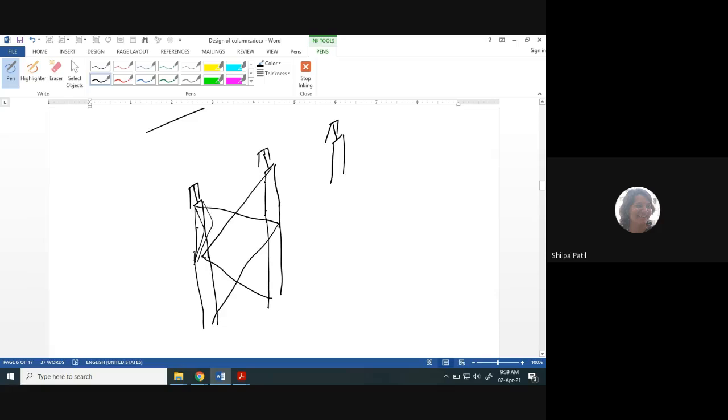Okay, here also, if the column will buckle, it will buckle between these two heights only. But when you consider this direction, the column is free to buckle to its full length because there is no support provided here. We do not provide the bracing like this. Otherwise, your entrance to the industrial building will get closed.